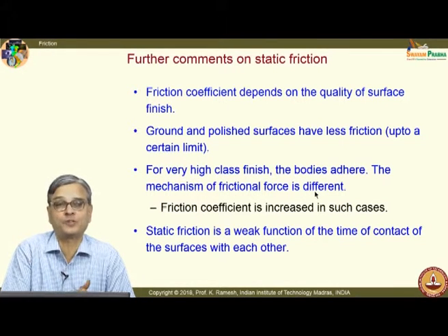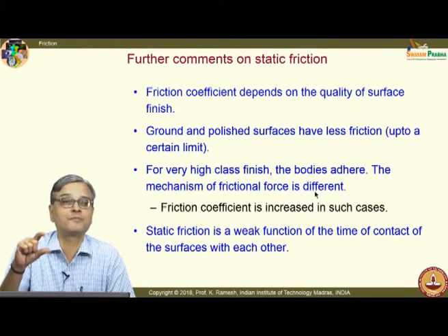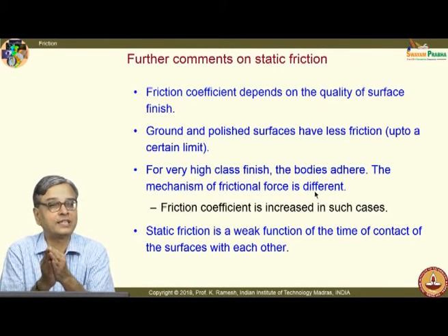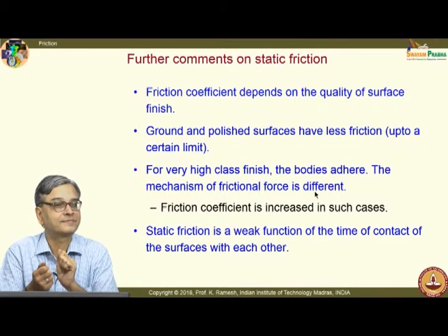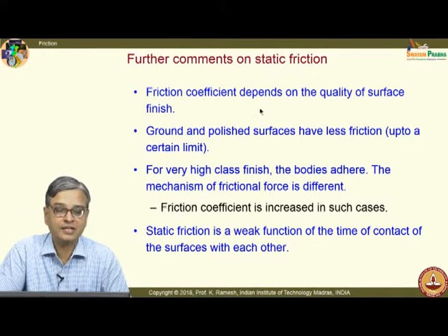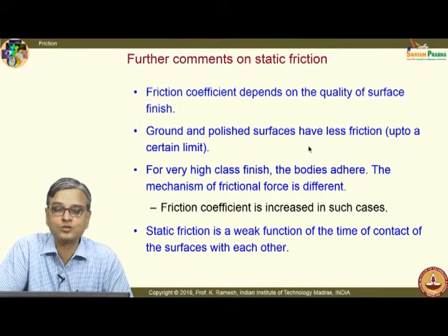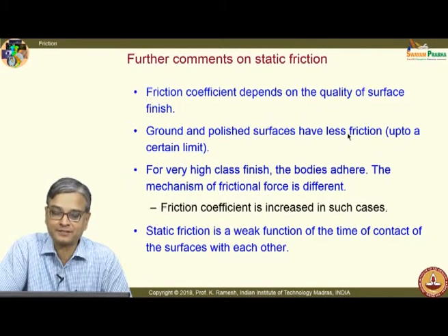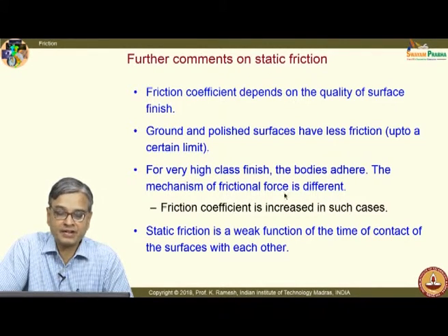Particularly when you go to a workshop, they will have blocks to find out the height and they are very highly polished, and when you put them together, it is very difficult to separate. So, in general, when I have a ground and polished surface, you will have less friction, but only up to a limit. The mechanism of surface behavior changes when I have a very high class surface finish and I have adhesion, and in such a case friction coefficient is increased rather than decreased because of the smooth surface.